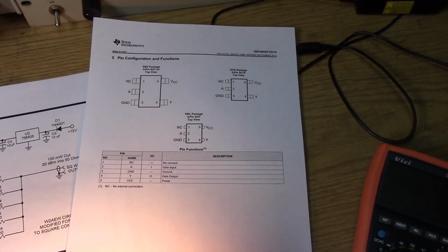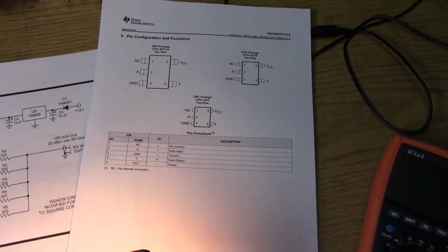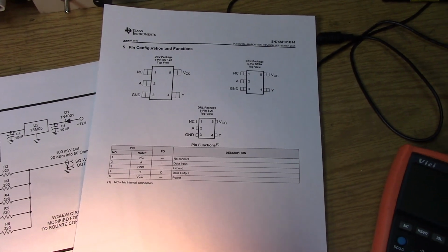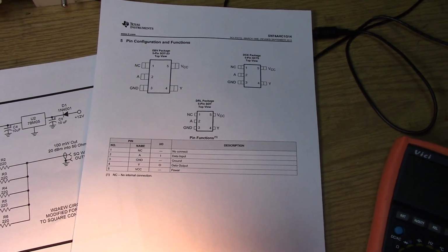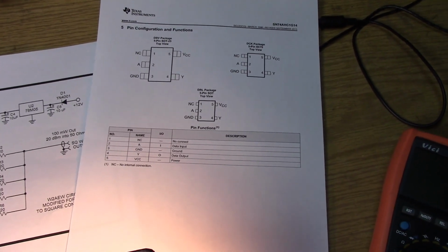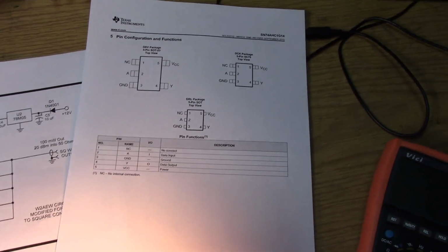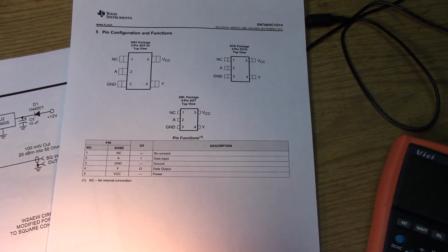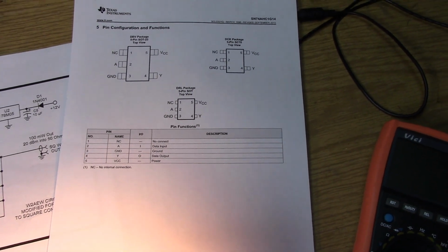The little SOT23-5 Schmitt trigger inverter is a package that you do not want to be breadboarding unless you have a proper technique or a board that you can buy that has the actual footprint of the part on it. Otherwise, you have to do some pretty fine carving on the board, and I attempted to do that with a razor knife.